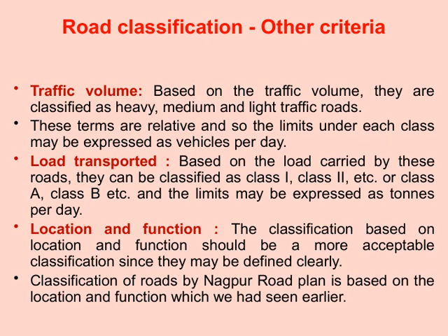Let's now look at some other criteria used for road classification. First, traffic volume. This is about how many vehicles use the road daily, and based on that, roads are categorized as heavy, medium, or light traffic. It's important to remember that these terms are relative, so the actual limits, like vehicles per day, can vary depending on the context.